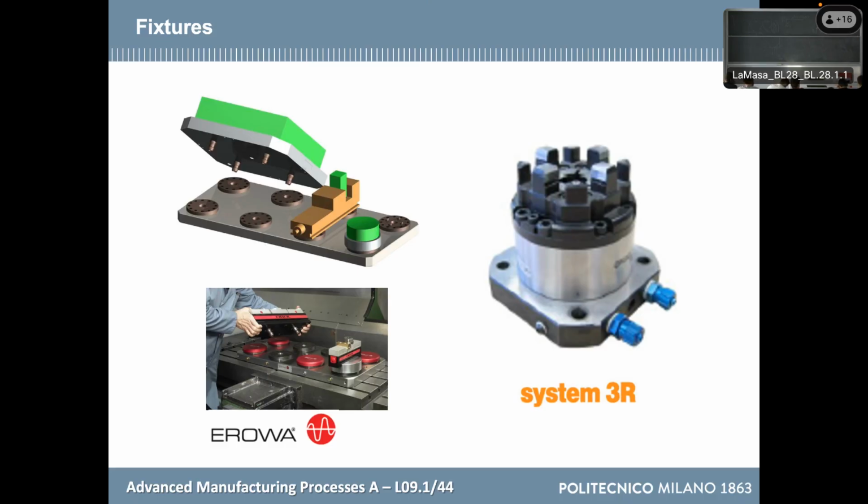There is a hidden risk here. Can you say something? Because you see that the part is attached to the pallet. The point here is, what happens when I remove the part from the pallet? We know that residual stresses are a bad thing, and if the material was already stressed at the beginning because of the previous processes, and I did not apply any thermal treatment for relaxing that stress, it means that when I remove material and I detach the part from the base, it will bend in order to recover, because the residual stresses are self-balanced. So, in other words, I put a stressed part on board of the table. Then I remove material. Since I have removed material, together with the material, I have removed also the stress. So when I remove it, it will bend for balancing again the residual stresses.